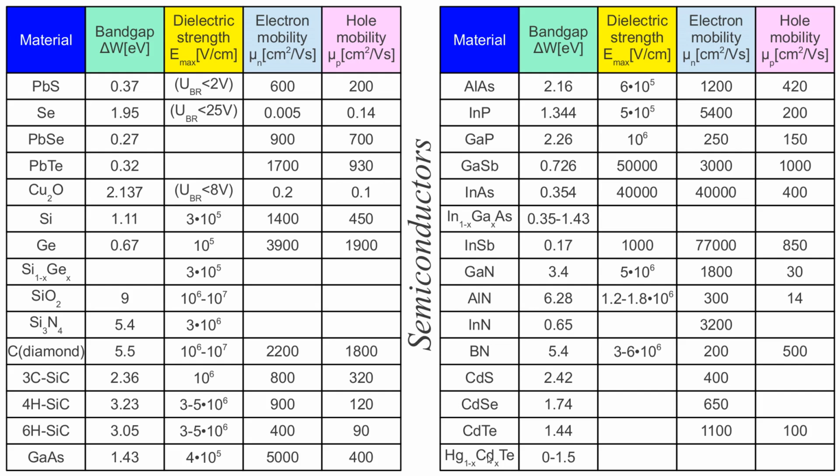And at very high temperatures, semiconductors like diamond, which is also a semiconductor but with a pretty wide band gap. At room temperature, it's quite a good insulator. Transistors can be built out of diamond, but operating at much higher temperature than room temperature. So this is the constraint we have on the other end. Silicon, with the band gap of slightly more than 1 electron volt, is almost by definition our semiconductor of today.